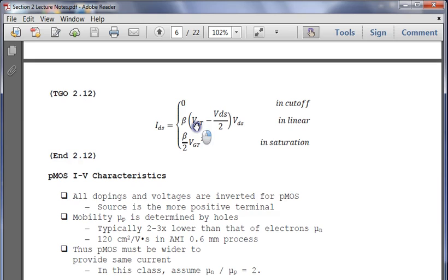Counting it down. Cutoff, we have the gate source voltage at 0. All the holes, barriers are in place. Once it starts raising, they start getting pulled away. Once we reach this threshold voltage, we create the inversion region. The inversion region ties the gate at the source to the drain, creates the channel. What happens is when we reach this saturation region, we end up creating instances where the channel gets pinched off.